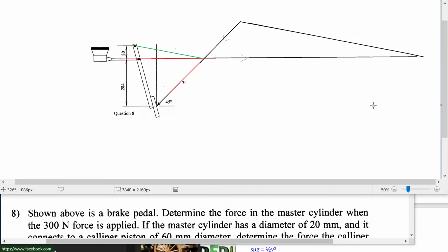You get the rough idea. So with this diagram here, if we know this is 300, then we can calculate the other values of the force being applied. So this is going to be like 3, 6, 9, probably about 1200, and the same concept. You should use a ruler and measure it off and do the scales accurately, but that's the idea of how you do that using the 3-force method.